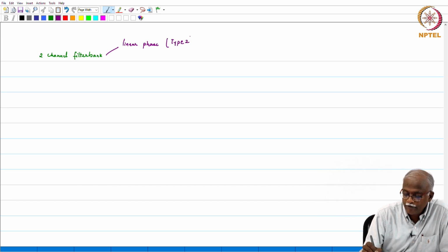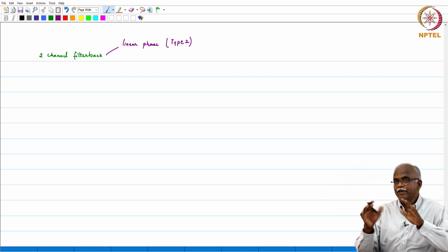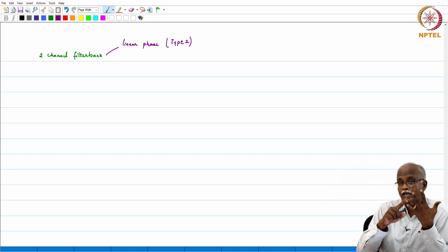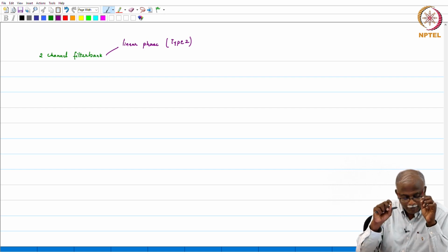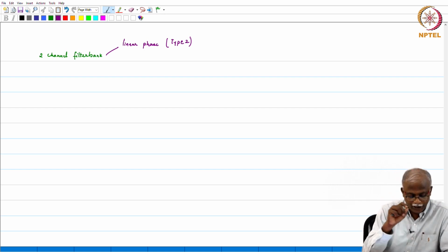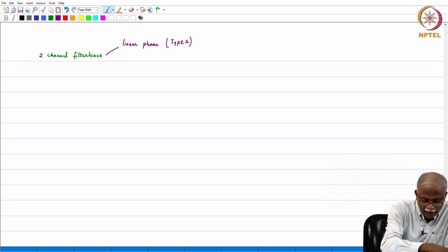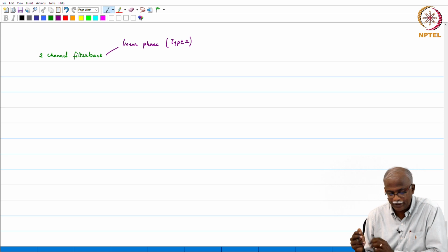This was very popular because it gave us a way to design filters that did not have aliasing, did not have phase distortion, and had very minimal magnitude distortion, which we could then optimize with respect to the condition that we have.